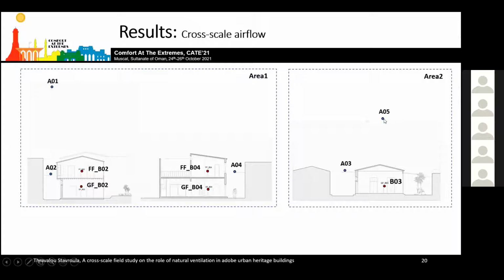And this is justified due to the difference in the reference height. The mean building height in Area 1 is higher, and so is the reference height in station A1. Also, Area 2 is located downstream of the main wind direction, and therefore it is affected more by the drag force of the upstream neighborhoods.